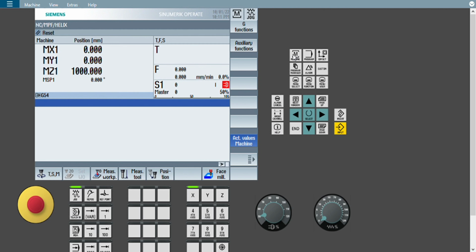In today's session we will see how to create profile pocket milling. In yesterday's session we saw how to create a standard pocket. What is the meaning of a standard pocket? A standard pocket is a circular pocket or a rectangular or square pocket, because we get that standard design built into our programming language. But if I want to create a different type of geometry rather than square and circular, what should I do? This is a very interesting question, and people are asking it, so on the basis of that question I am trying to create a few things for you.